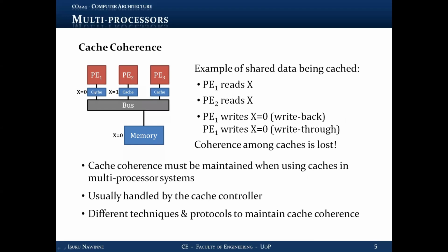If we go back to the previous slide, the cache coherence example, the issue was that we had different values for the same address in these two different caches. Now, when processing element 1 performed the write, x equals 0, if there was a snoop bus, processing element 2's cache controller will listen to that write broadcast through the snoop bus, and since it also has the same address in its storage, the cache controller can now mark this particular block as invalid.